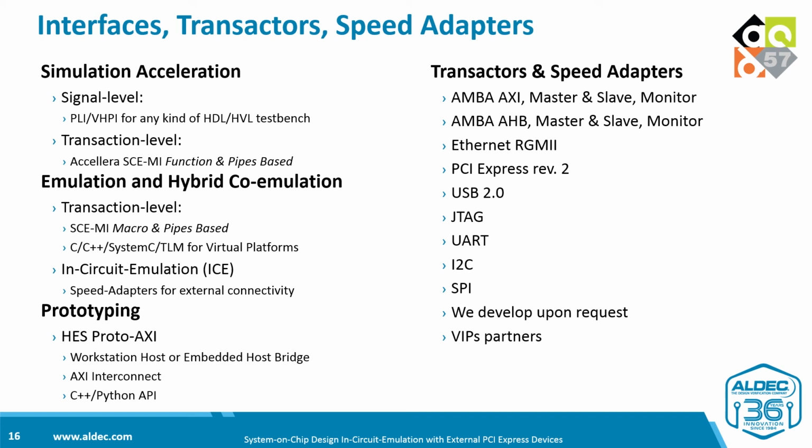Emulation and hybrid co-emulation are supported by the transaction level interface, which is compliant with the Accellera SCE-MI standard. Additionally, Aldec provides SystemC and TLM wrappers to facilitate connection with popular virtual platforms. In-circuit emulation that often requires connection with external devices running at higher clock rates is supported by the speed adapter dedicated features and multiple clock domain support.